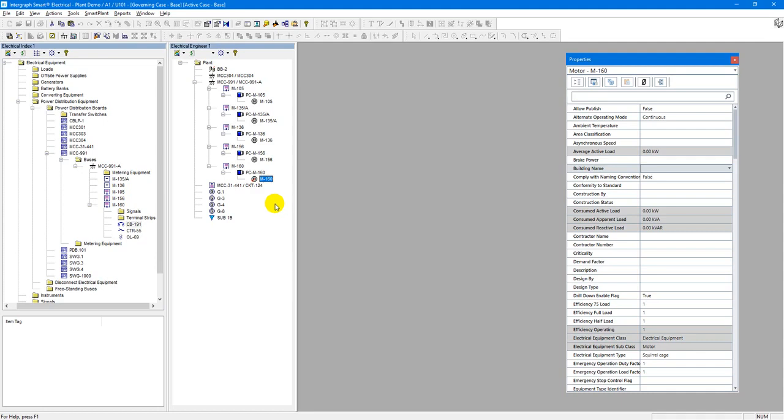In this short video clip, I would like to demonstrate how to enable the automatic selection of the circuit breaker rating in SmartElectrical based on the full load ampacity. So here I have the classic example of the standard direct online motor feeder with the circuit breaker as the